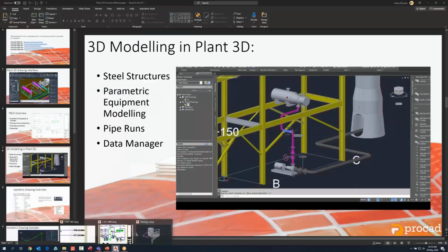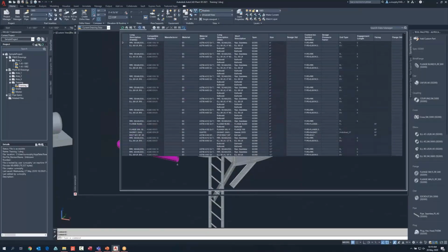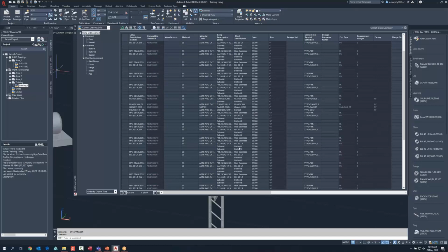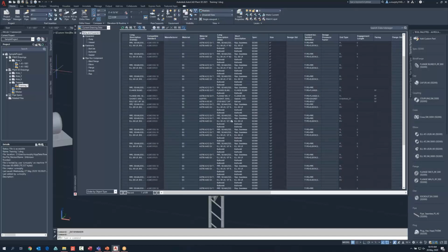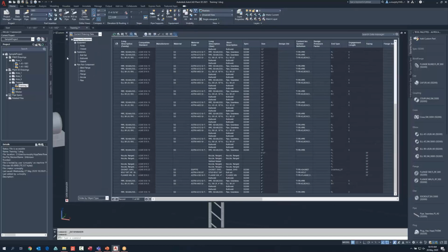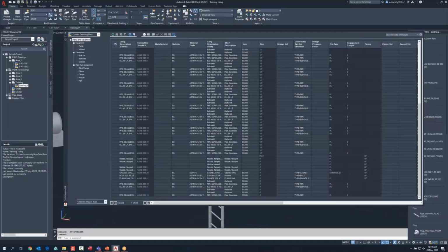So just lastly there on the 3D model, we do have a data manager here as well, and if I click on the data manager, this will give you the information of all the pipes and all the flanges and all the elbows and T-pieces that are required to make this. Additionally, you have the weld types between, so these are butt welded. You could have flange connection, you could have, say, different types of welds. So this will give you kind of the entire bill of materials, if you will, required in creating this model which I have created.